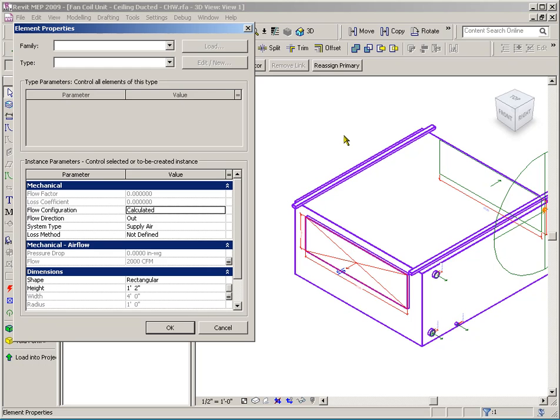And then you say specify equipment for the system. You're specifying the parent object that serves those children. Your system's already created at that point. It just goes back and says, here's the parent equipment serving this group of diffusers in my zone. VAV systems are a very good example. This fan coil unit is not terribly different from a VAV, in that it is a parent object. You don't create a system from this, you create it from the diffusers or the registers or the grills.